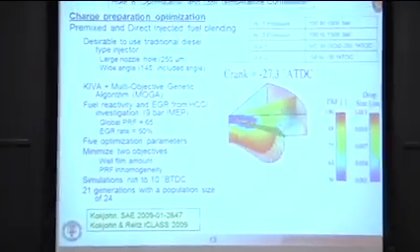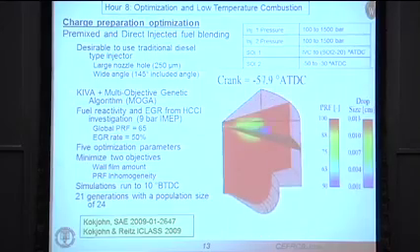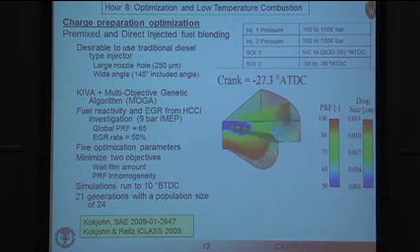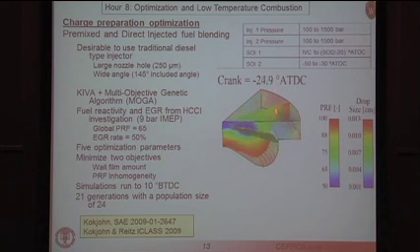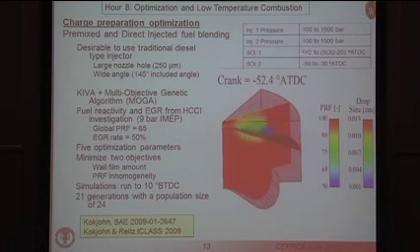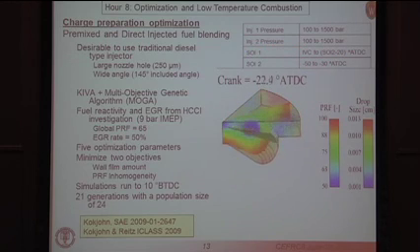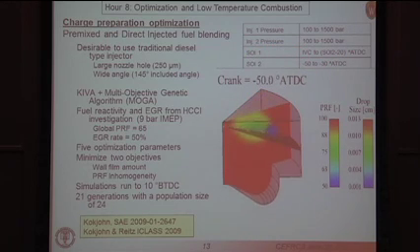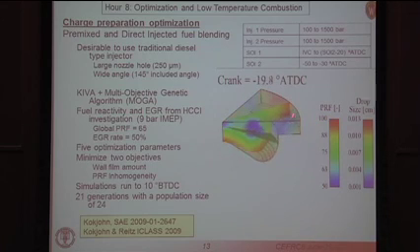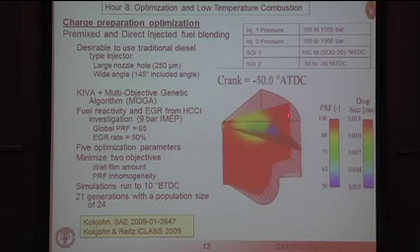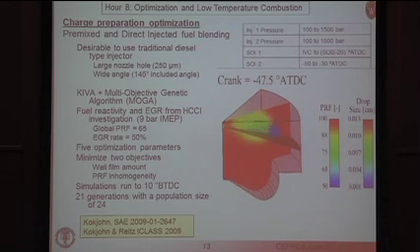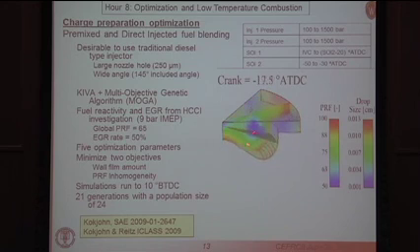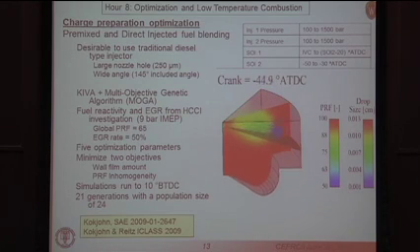Red corresponds to PRF 100, or just gasoline. So at intake valve closure, we assume the chamber is filled with gasoline-air mixture. And then the two injections that we discussed take place at the injection times that I discussed. We have a first injection that kind of targets the region above the piston here and changes the octane number of the gasoline to an appropriate value. I'll talk about that in a minute. And then a second injection that's targeted into the bowl that turns out to be the ignition source.